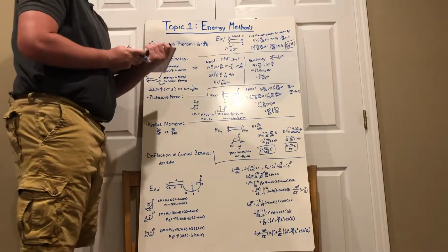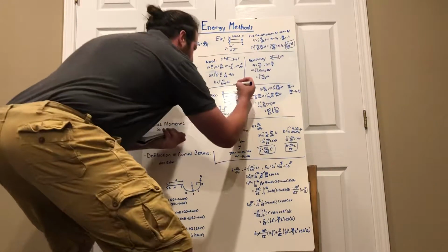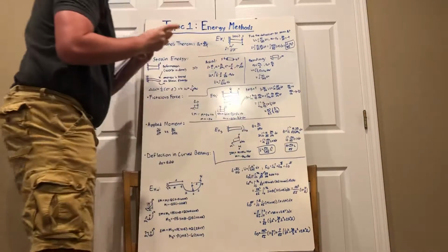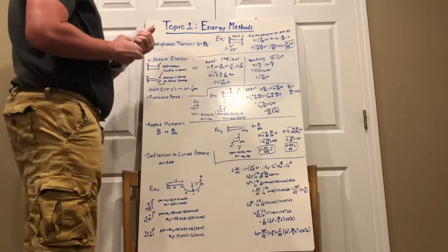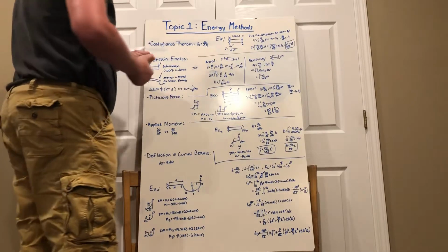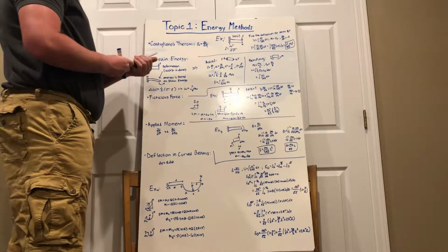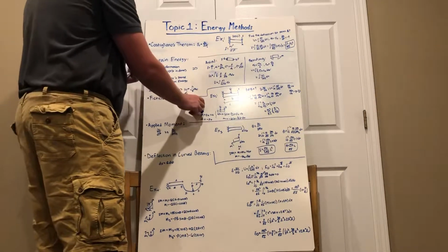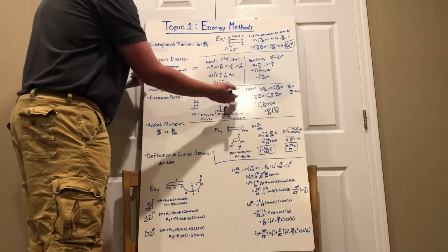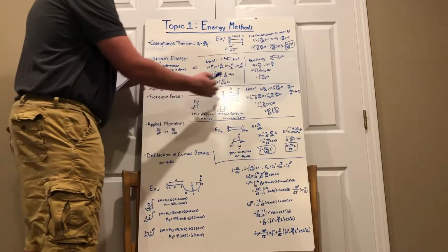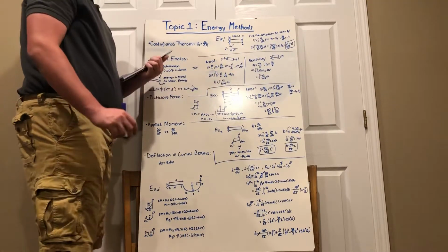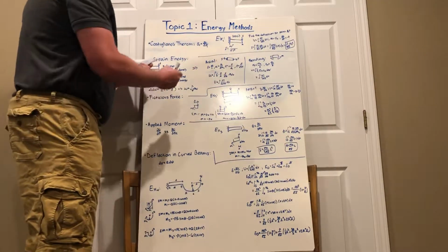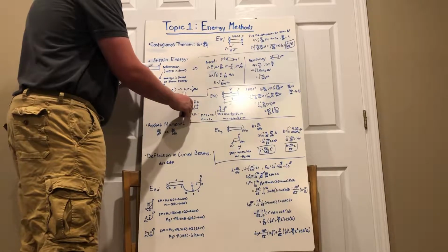So, how are we going to do this? Well, first let's apply our fictitious force here at point B. Let's give it magnitude Q. Okay? So, we want to know what this is. So let's first draw free body diagrams and try to find the moments. So let's start by analyzing this problem from the right-hand side. So what we're going to do is make a cut here. We're going to analyze it like a normal moment problem and a deflection problem. So let's make a cut and try to solve a moment about this side, right?